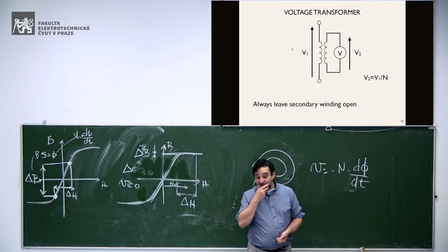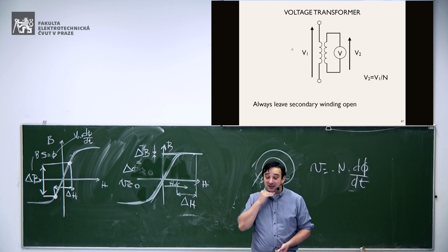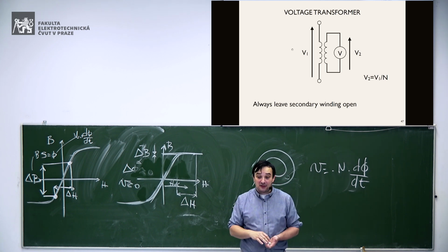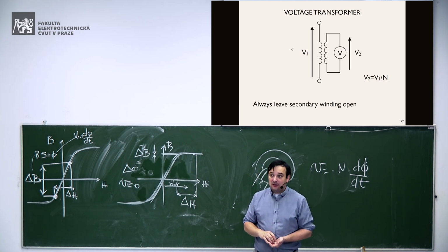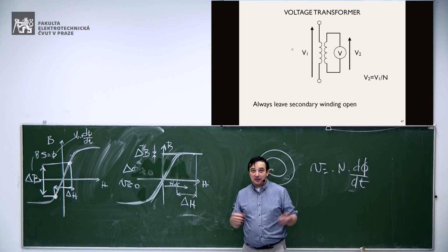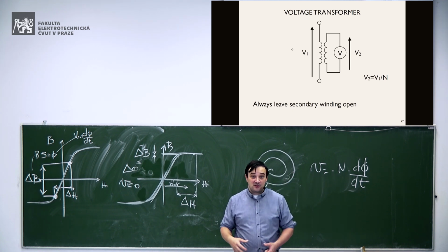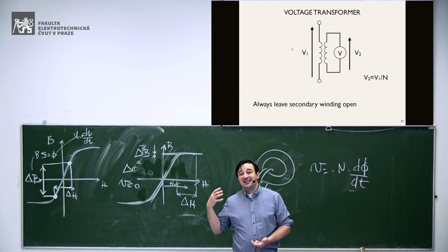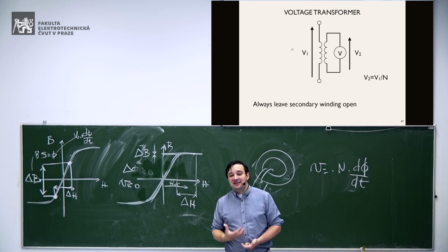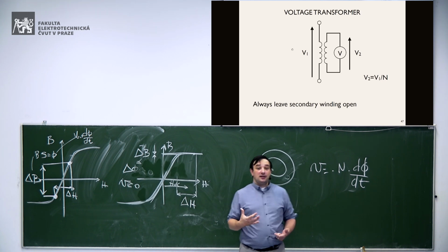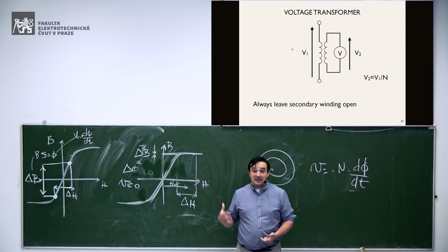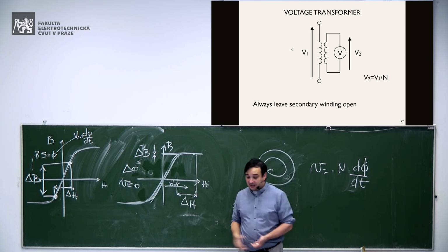This typically happens for meters of industries. For meters that we have at home, typically they use a shunt resistor. But for industries where you have very, very large current, typically they need to use some current transformer to measure the current, and therefore you have this kind of problem, okay?